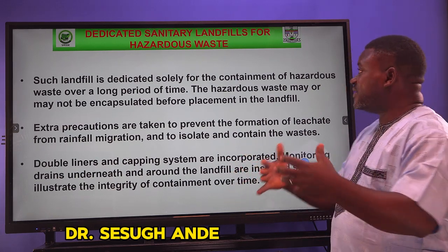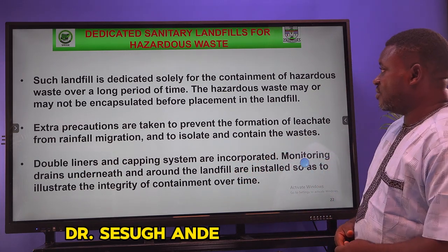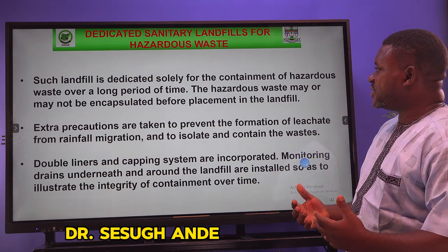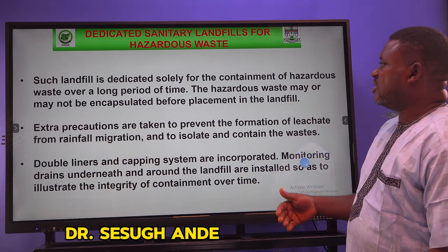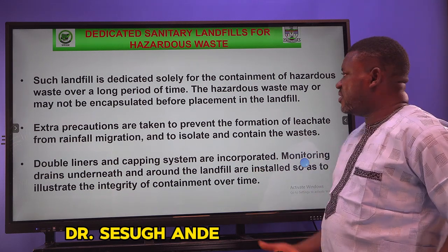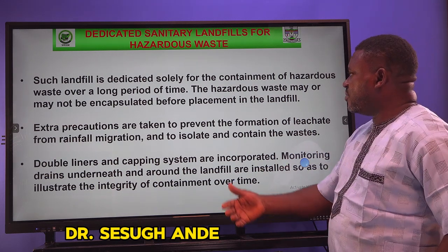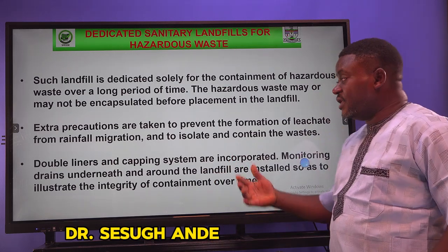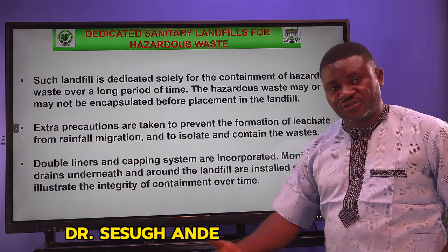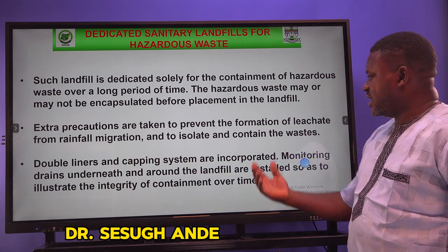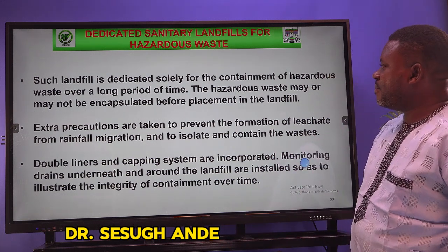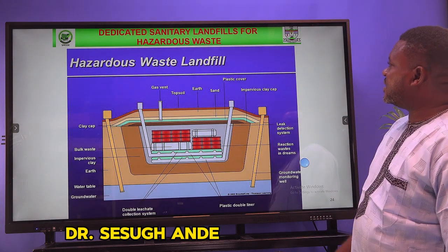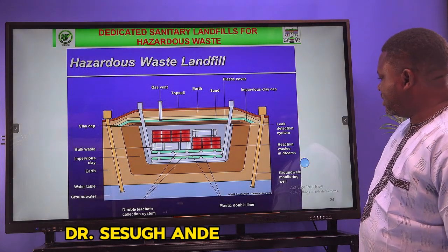Then we have dedicated sanitary landfills where these hazardous materials could be trapped. Such landfills are dedicated solely for the containment of hazardous waste over a long period of time. The hazardous waste may or may not be encapsulated before placement in the landfill. But here, extra caution needs to be taken so as to prevent leaching of these materials into the water system. So this is a typical dedicated sanitary landfill for hazardous materials.